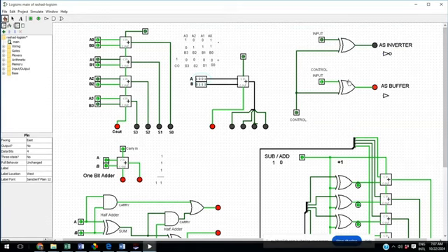Okay. We talk about the subtractor. The subtractor idea is to have the two's complement of a number, which is the ones complement plus 1. There is a control, and an exclusive OR can do the job, with the control at 1 or 0. If it's 0, it is used as a buffer, and if it's 1, the exclusive OR will act as an inverter to invert the number and give us the ones complement. Let us look at it here.